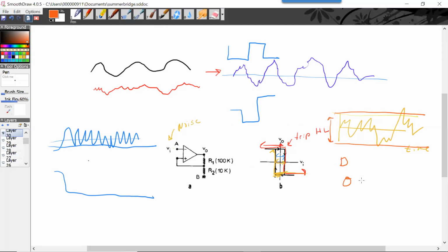But in this paper, it's called root mean square. And the equation for that is 1 over the period, integrated over the whole period. X(t) is the signal in question, and you square it, and it's all done with respect to t, and you take the square root. All right. So now, the RMS value,